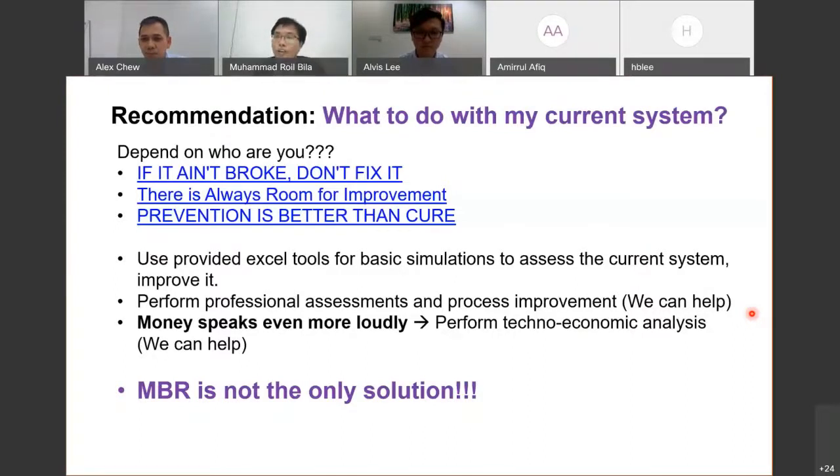It depends on how you operate the MBR. If the membrane is immersed inside the bioreactor, it's impossible. It will be aerobic. But if you operate it separately, in a separate tank, maybe it can turn anaerobic, but most likely not. Why? Because we also have a quick sludge circulation in MBR. So a good design should not allow the condition to be anaerobic in the membrane tank.